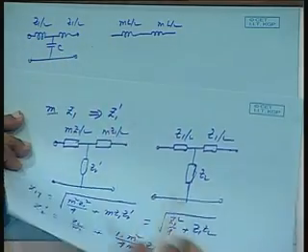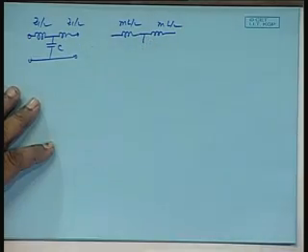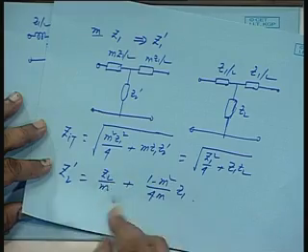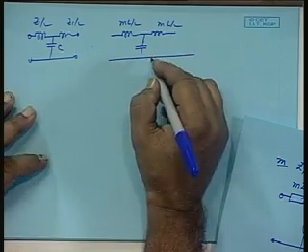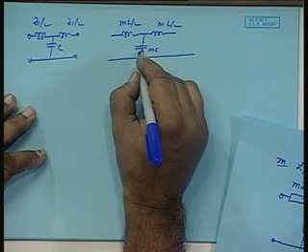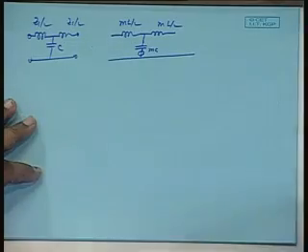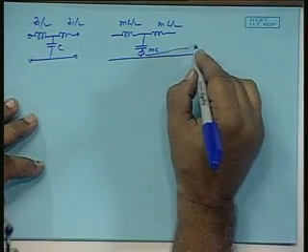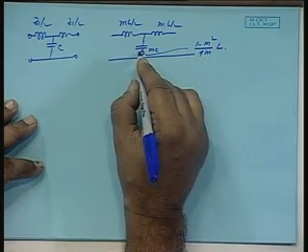If I take an LC combination like this, then it will be this one. And in the shunt element, it is Z2 by M. Z2 was a capacitance, so it will be M into C plus another element which is given here as 1 minus M square by 4M into Z1. Since Z1 is an inductive element, this additional element will be 1 minus M square by 4M into L. So, there is an inductance here.